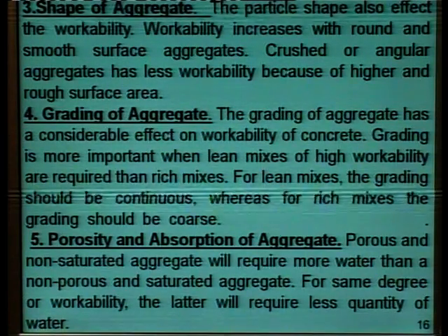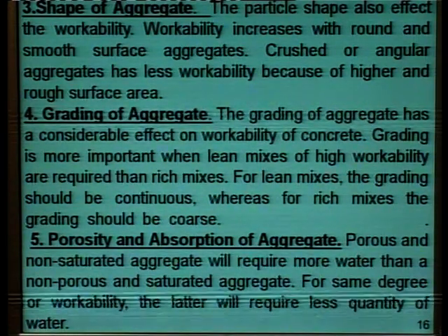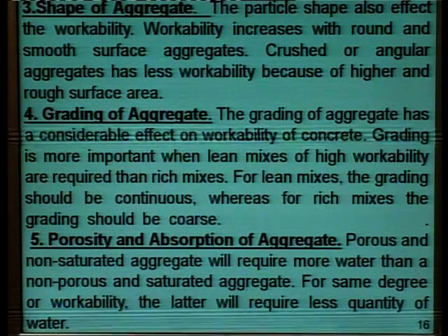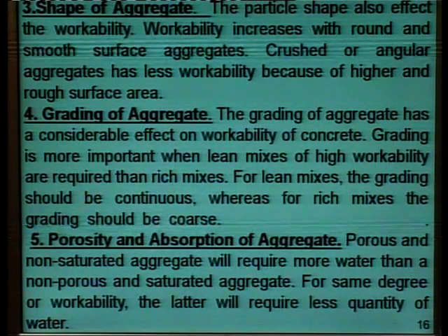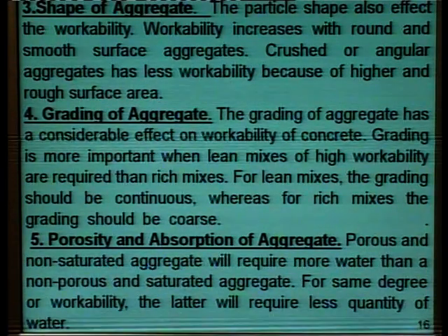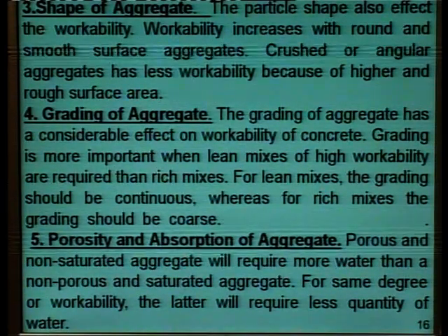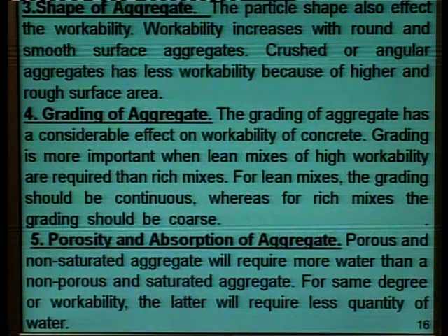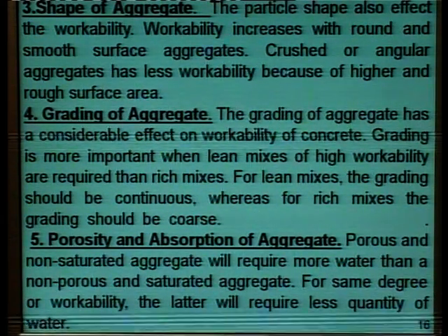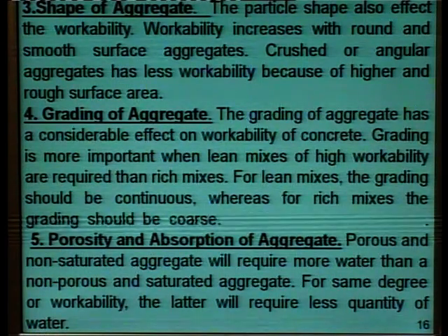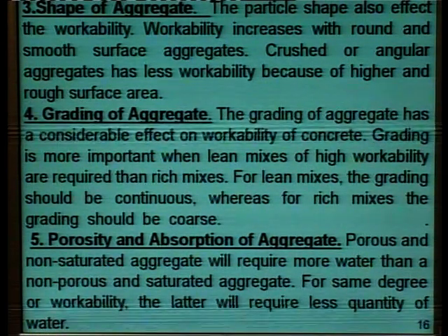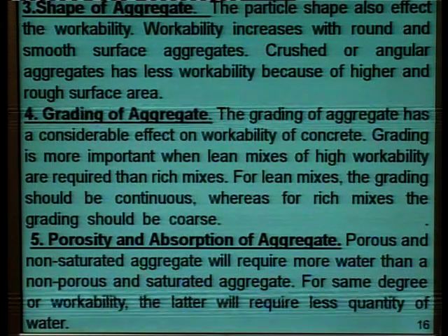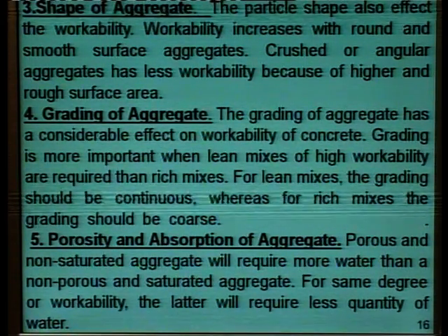Fourth is grading of aggregates. The grading of aggregate has a considerable effect on workability of concrete. Grading is more important when lean mixes of high workability are required than rich mixes. For lean mixes, the grading should be continuous, whereas for rich mixes, the grading should be coarse.